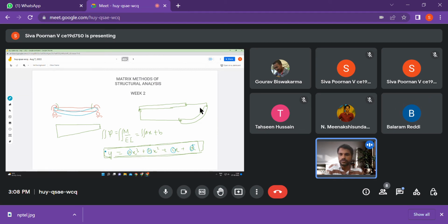This is true just because we assume that the loads are being applied at the ends only. When we said that the moment diagram is going to vary linearly, we inherently assumed that the moments are applied only at the ends, right? We are not considering any intermediate loads. If intermediate loads are there, then moments will not be linear. Moment can have a complex variation, right? In that case, whatever argument we are making is not valid, right?